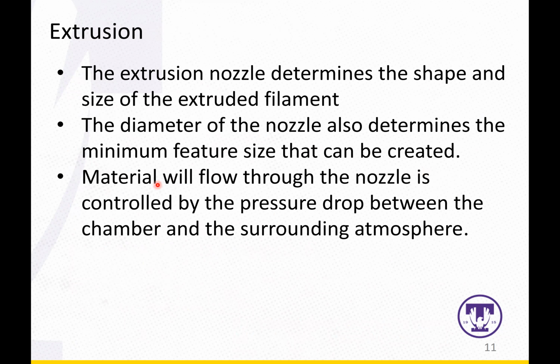And I mean, obviously, if the nozzle size is bigger, you will have a bigger feature size, and the smaller, you will have a smaller feature size. But still, you need to balance the feature size versus the printing time. So if you choose a too small nozzle, probably you will need more time. So that's the price you have to pay, right?